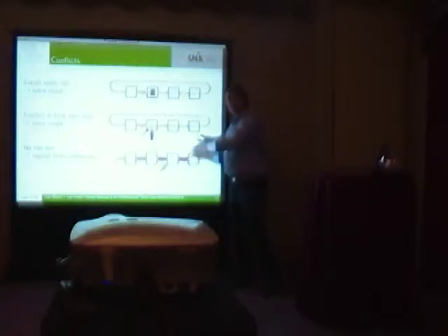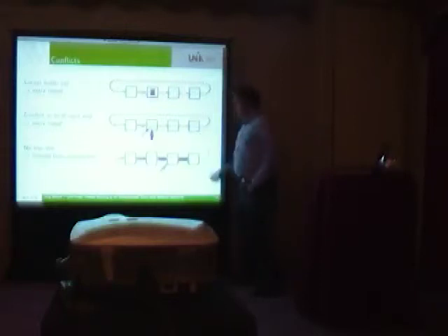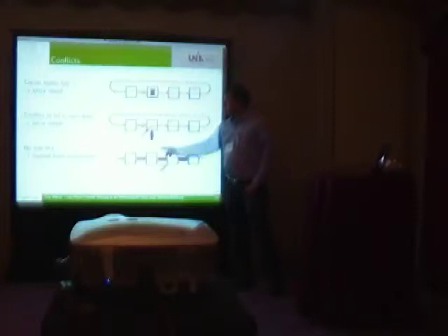And one problem is, I showed you the example that you need a free slot in this ring, and the problem is what to do if you don't get one. So maybe this one won't send. If this ring is constantly filled and has enough messages or flits, you can completely starve this node. What you can do is have some backlinks here. It's just 1 link with 1 bit to demand a free slot from the preceding node.